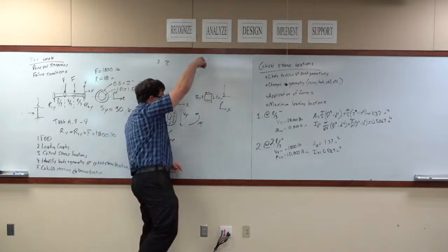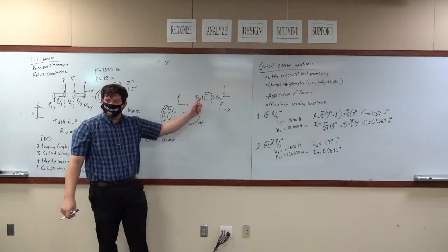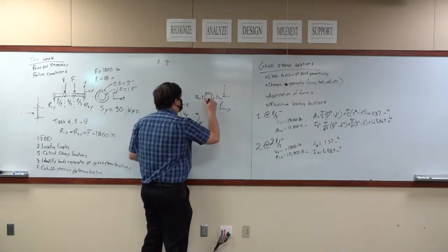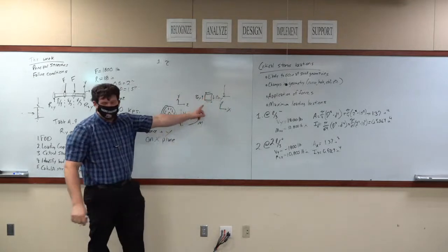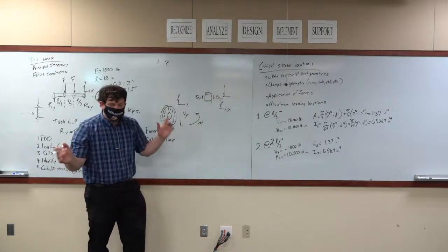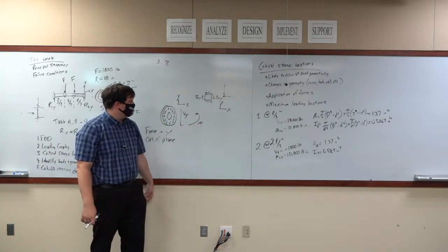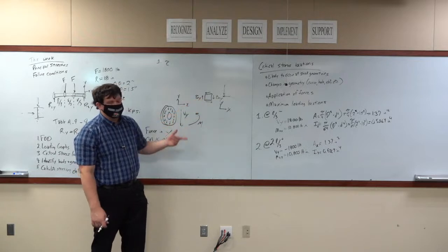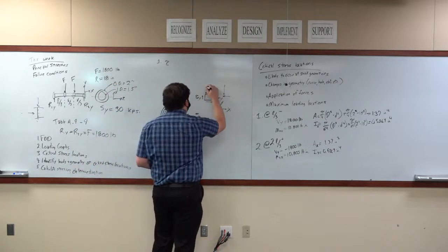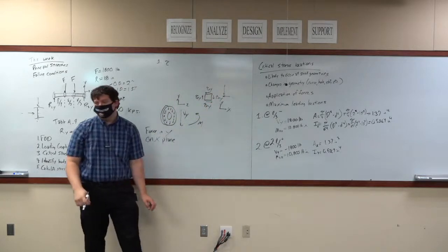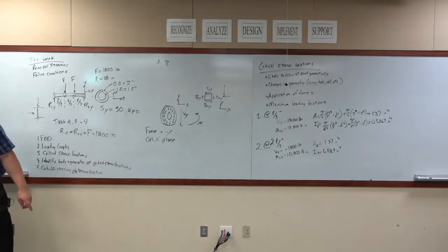If you're looking down the Y-axis at it, that's how you see the face. It extends out in the X direction and the Z direction. So this occurs on the Y face. In what direction is it acting? It's acting in the X direction. So this also happens to be tau xy. All of these are. One tau xy creates 3 other tau xy's on the same unit cube.